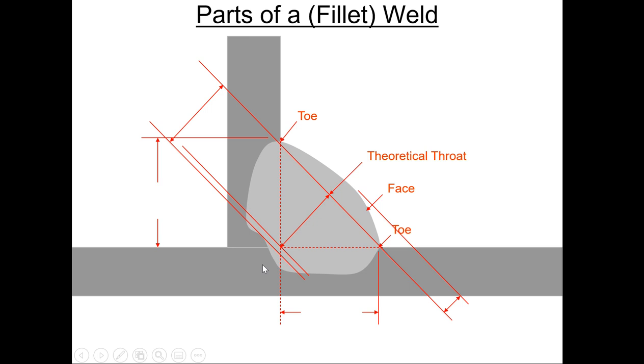Not as big a deal for you guys when it comes to the size of a weld. Professional welding people that weld every day weld to certain sizes. You guys don't have to worry about that as much as meeting your goals for the amount of fill you have. The effective throat adds the thickness, or the depth of penetration. The next is the most common for the maintenance application, where you've got the vertical leg and the horizontal leg.